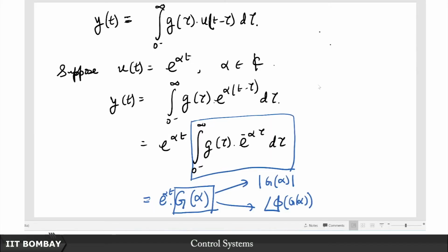So let us apply this technique here. You will see it turns out to be the same thing. There is, however, something that needs to be said at this junction. What is this response that you see here, after all? We have seen that the total response of a system is the 0 input response plus the 0 state response. Now this response is neither; it is only one part of the 0 state response. That is, if you set the initial conditions to be 0, then this response will be sitting inside that response, but this is not the entirety of the response.